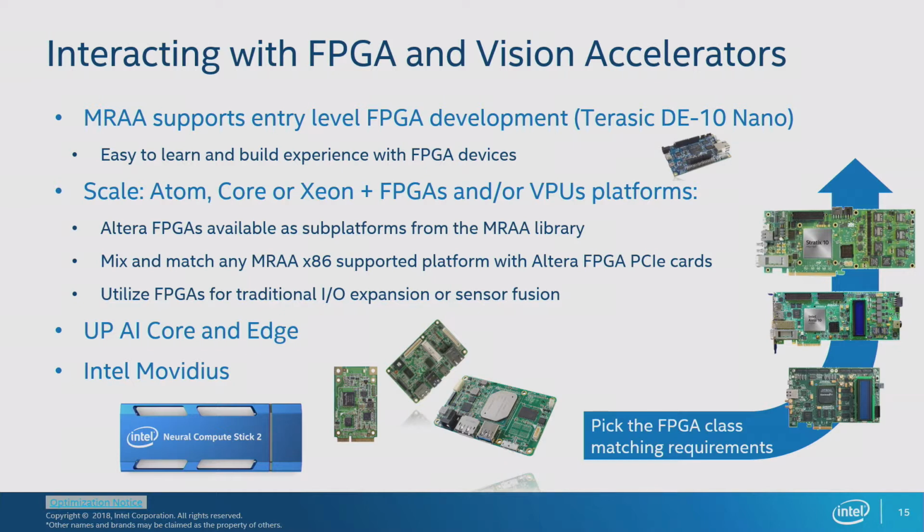And then you can easily take that and scale it up. So you could support other FPGAs that are available, and they are usually exposed as sub-platforms from the MRAA library. So think of sub-platforms as extensions to the MRAA library, so it's something that's not necessarily on the device that you support itself, but like an add-on, right? That would be a good word for it. You can also mix and match x86, ARM, and FPGAs, as I was saying. And the best part is you could use them for traditional I/O expansion and doing level shifting and whatnot, making sure that you have enough outputs to drive all your sensors.